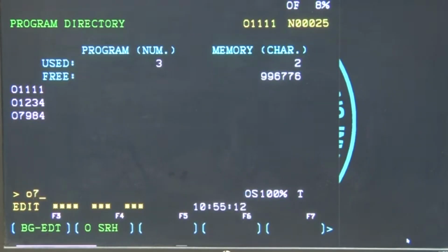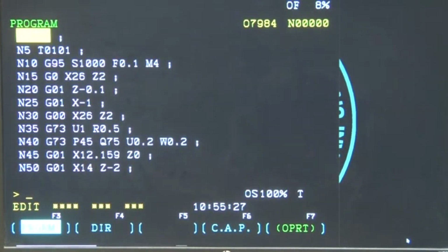the X minus 1, that means this is given as a facing cycle, all right. X means it is in the direction perpendicular to the axis of the workpiece. So, at this moment we are calling the entire program which is already there, all right. So, you can see that in N25 here this is the G01, okay, and X minus 1. So, G01 is the linear interpolation, this is remaining. In fact, if you do not give the G01, it will also take the same from the N20, and here it is given X minus 1. So, we are facing.